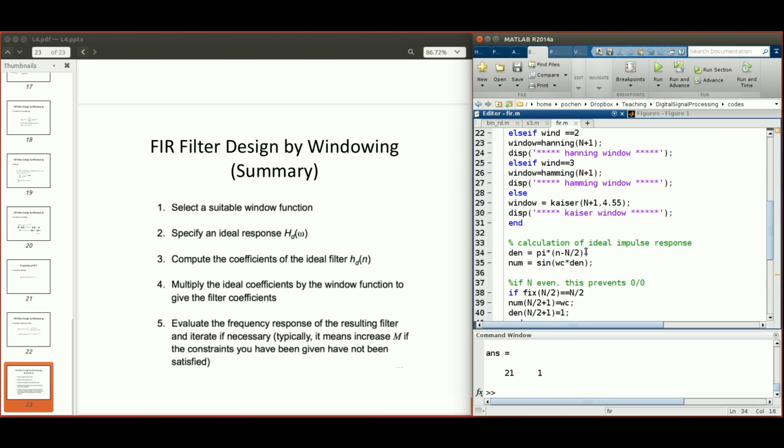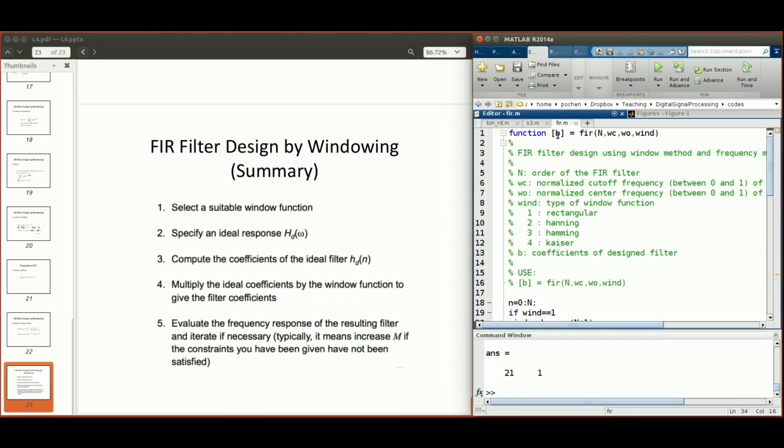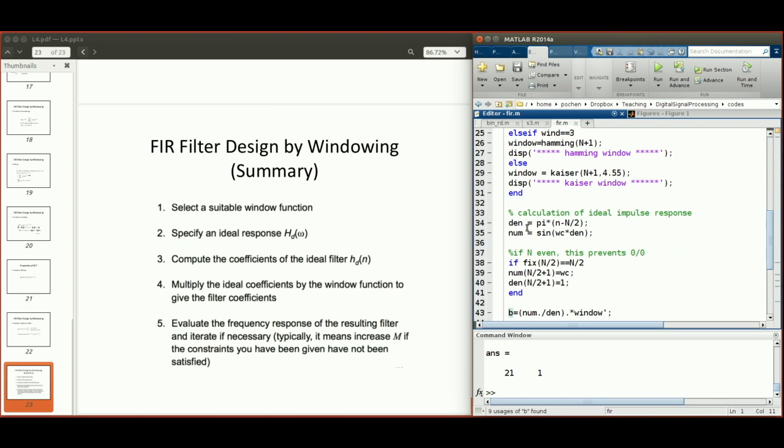But in any case, the output of the filter doesn't really have a horizontal axis associated with it. So you can use B in the zero phase case, which has to be a symmetric time axis with non-zero amplitudes at negative time, or you can use a causal horizontal axis with B. It doesn't really matter. But here, when you compute the sinc function, it assumes that the peak is at big N divided by 2, half of the number of points.